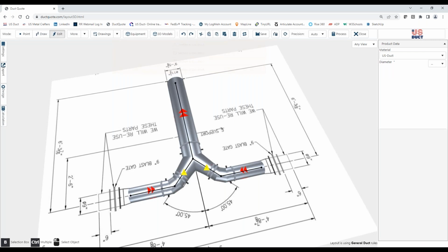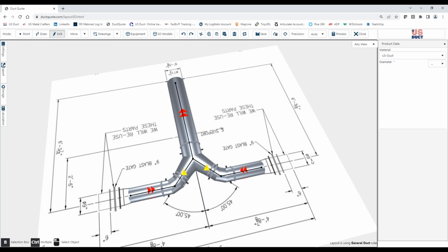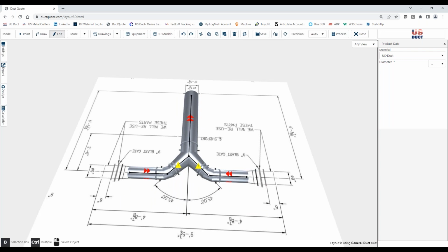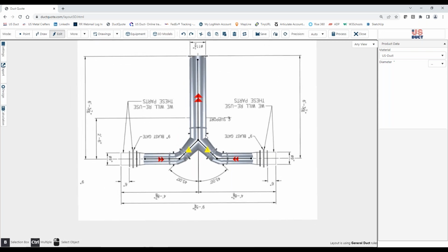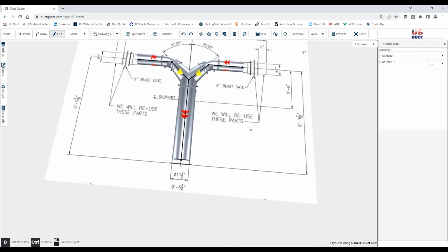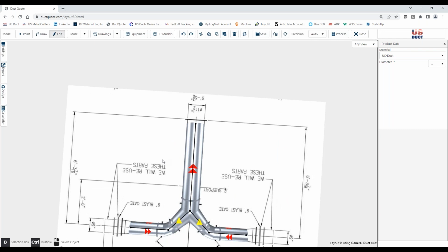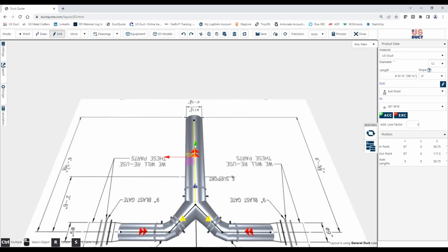And you've got tight tolerances where trunks have to run, if that's the issue, and you're combining two subsections from opposite directions. Well, you might not be able to use a Y branch because of the actual position of where those opposing subtrunks are coming from. You can see here that where they had given the actual size of their combined subtrunk, one of the issues was that they wanted an 11.5-inch diameter piece of duct. Well, we don't make that. We make whole integer diameters, if you will.